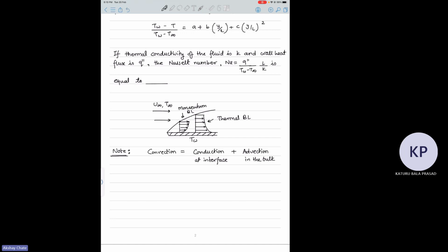Typically, if it is a forced convection, the convection will give you a very high rate of heat transfer, and that is why it is preferred. So wherever you need to take out heat or to supply heat to any substance or surface at a very high rate, there typically forced convection is used. And in some places where the heat transfer rate is not that high, you can use natural convection. So I'm talking in very vague terms here, high, low, because this is an introductory class. But the point is, we'll talk about those later also when we discuss them in detail. So that is one thing.